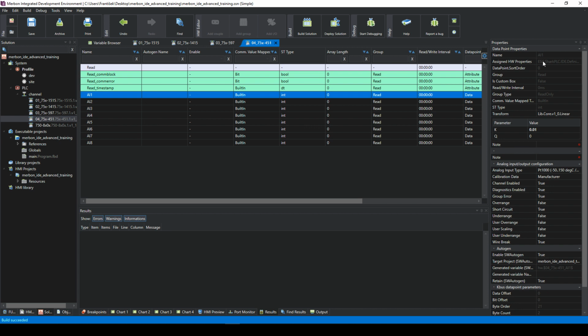Here you can see there is nothing, there is no type to choose from. This is set by the manufacturer of these cards. So Wago doesn't use this multiple choice for each analog input. So you have to buy the correct card for the type of measurement.